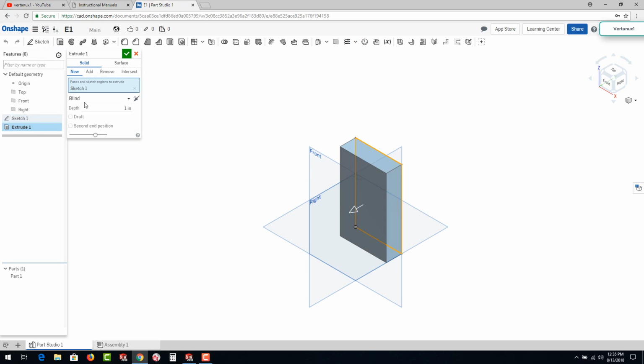So we could click on that, and notice it takes the boundary condition that we drew and enables you to grab this arrow with the mouse button and drag it forward or backwards. And essentially, you could over here put in an explicit value. So for conceptualization, it's nice to pull on the arrow. Once you've got your numbers down, go ahead and type in 0.5 up here, hit enter, and you'll see it will update. And just up here, hit the green check mark.